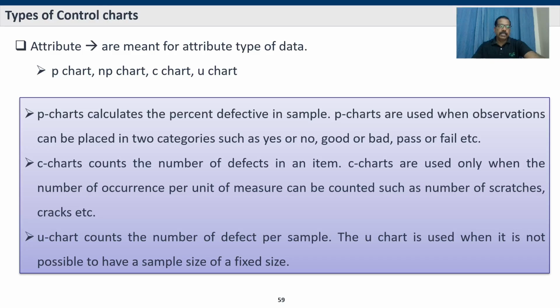So last video we discussed the X bar, R bar chart numericals. 4 examples we discussed. It's pretty simple. X bar, R bar calculation, process capability calculation, population standard deviation calculation. How to calculate 3 sigma X bar or 6 sigma prime we discussed. So these are all the things that were important in terms of X bar and R. So that all comes under control charts for variables. Now we'll be discussing the control chart for attributes.